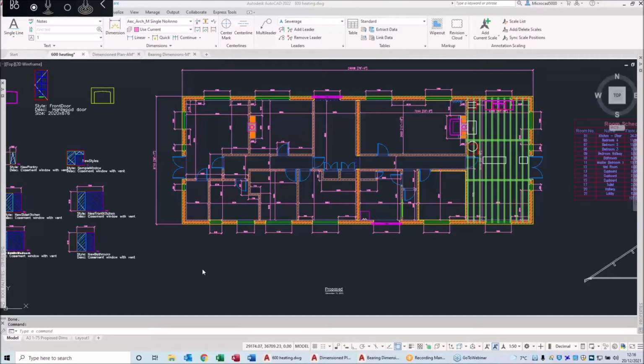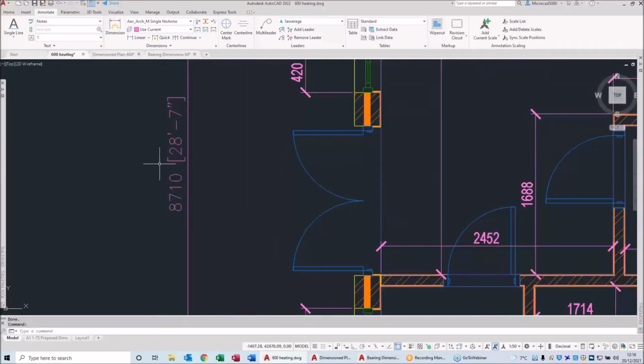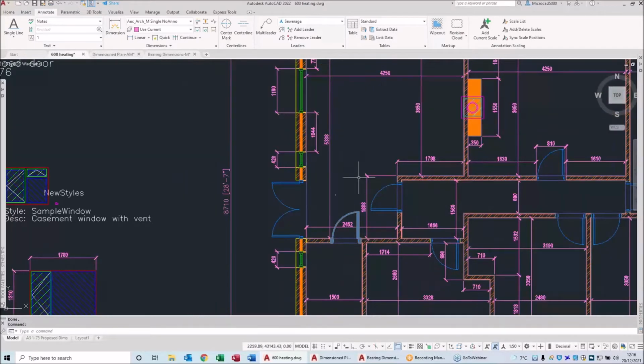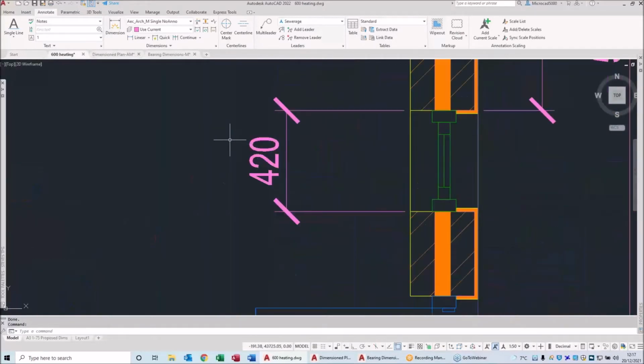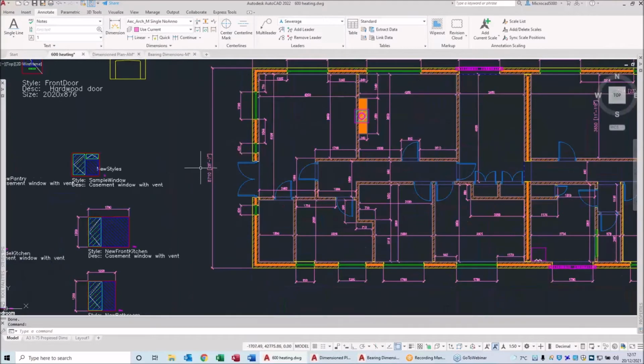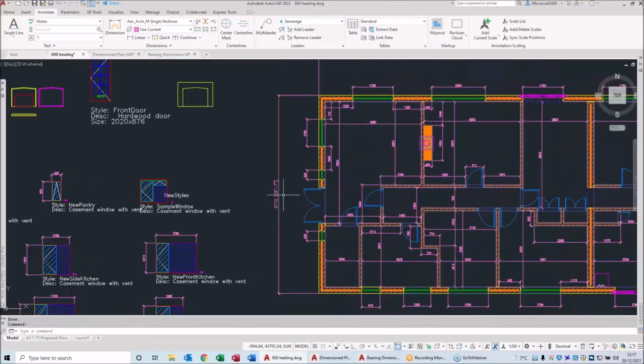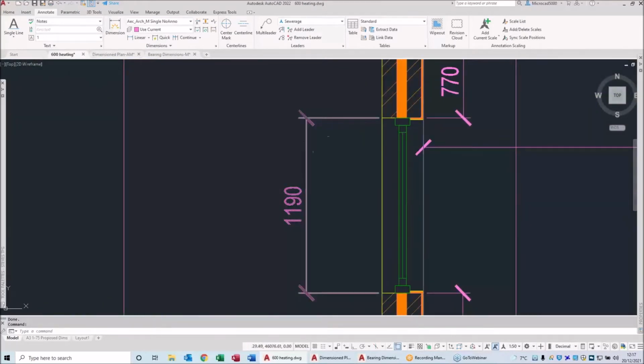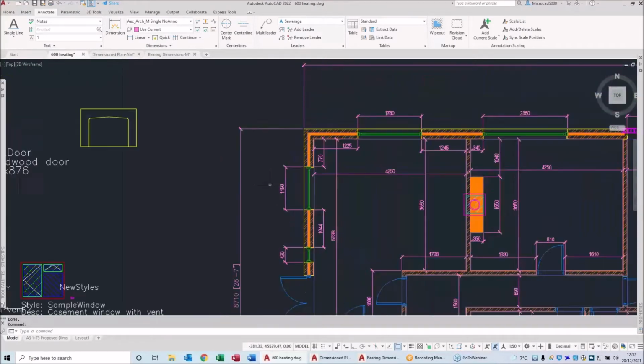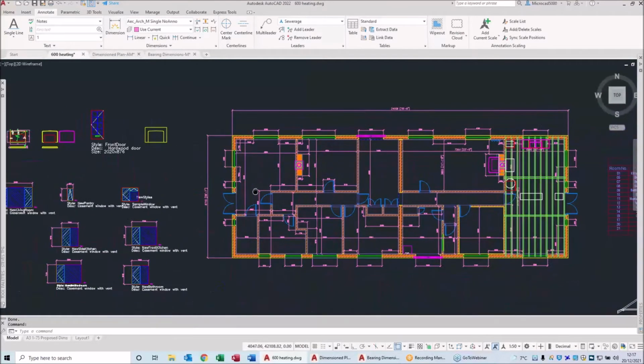Okay, so we're in AutoCAD. You can see here, in a drawing file, we have some dimensions. Now, in this particular drawing file, we have got 2 dimension styles. One dimension style showing just the numbers, and another dimension style showing the metric and imperial dimensions in there. So if you work for the states, you can put in alternatives. They've got tick marks in here. Look, you can put arrow heads on there as well, if need be. So that's also set up in the dimension style.